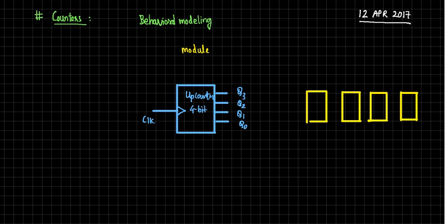Topic: we are designing counters in Verilog. We are going for programming. Structurally, we should specify how the outputs are connected to the inputs, but behaviorally we don't need to. That's the difference between structural and behavioral. You don't need to specify how the outputs and inputs are connected and so on. So I'll simply draw the structure just for reference, which we are not going to use.